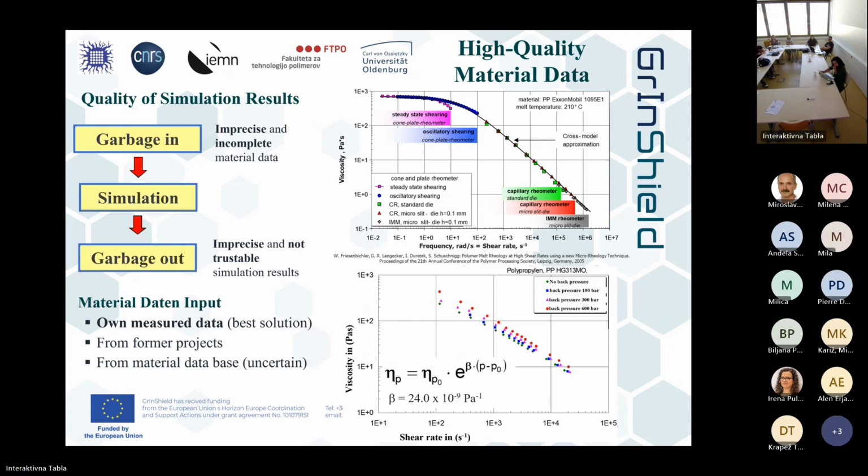But then we made a measurement where we applied a so-called counter pressure against the outflowing melt. The piston pushes the melt down, and we have a counter pressure. If we raise the pressure by 100, 300, 600 bars, you clearly see viscosity goes up.